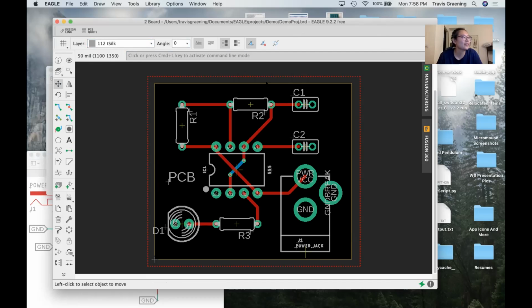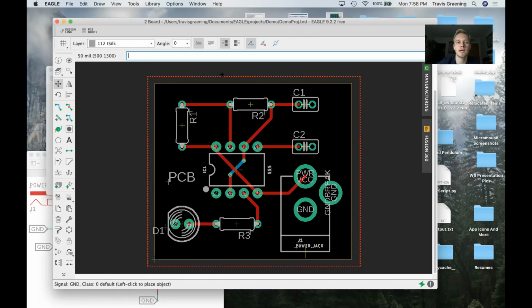I'm not sure about the SVG into the silk screen, but I feel like you can. Oh yeah, you can. There's a way. And Eric, to your question, yes, you can shrink or make your polygon larger. Just click the move option and then click on a side of the polygon and then drag it.